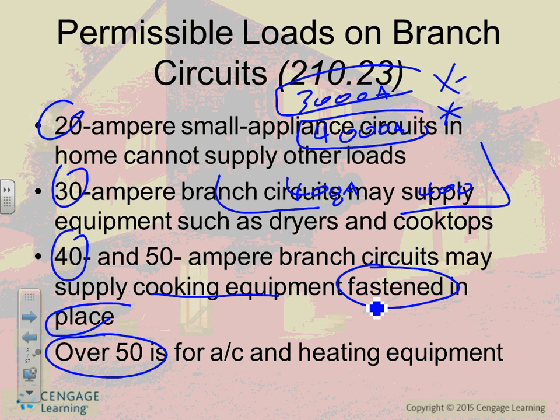If you need more than two services, what we typically do, guys, is we start going to medium voltage. Instead of giving you a 480 system, we drop the 480 if you need more than two services, and we start giving you a 13,800 volt service. They call it the primary. You get your 13,000 like the Mayo Clinic and the building that we did.